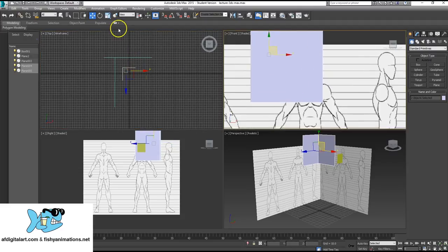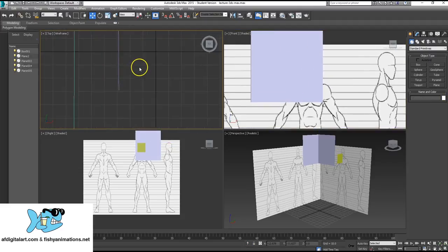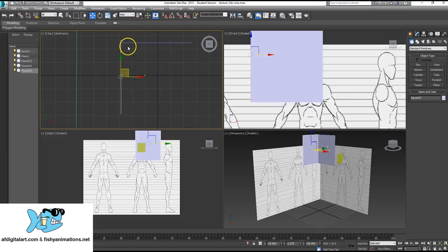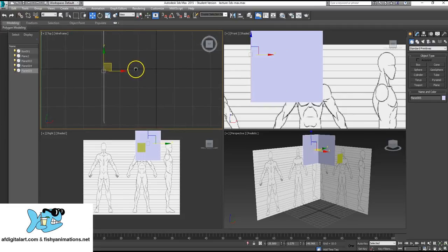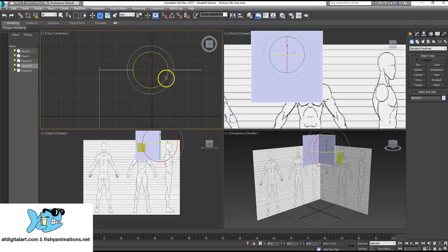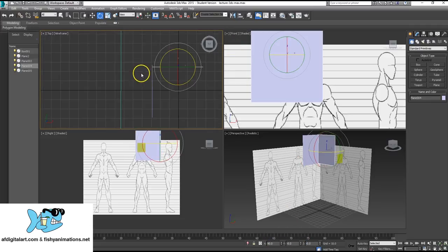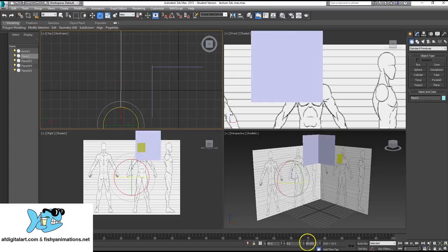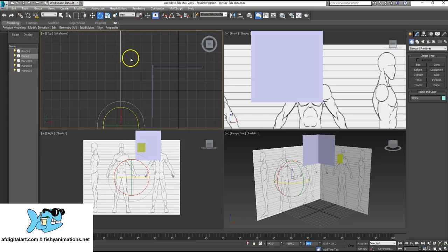Okay, now what I'll do, I'll make sure your planes are as close as they can be. Perfect alignment. If you have to, use these control properties down here. Noticing this could actually be -90. This plane here, that's 90 degrees, perfect. This plane has an 89, so this should actually be 90. Whoops, 90. There we go.